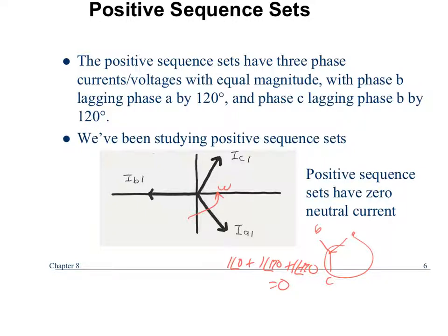A positive sequence system does not care if you have a neutral connection or not, because it sums to 0. Here's a key thing, and if you're taking notes, you should highlight this: for positive sequence networks, you couldn't care less how the system is grounded. It does not matter in any way, shape, or form. It's irrelevant. You can neglect or ignore the fact that there is a ground there. As long as it's balanced. It has to be balanced.